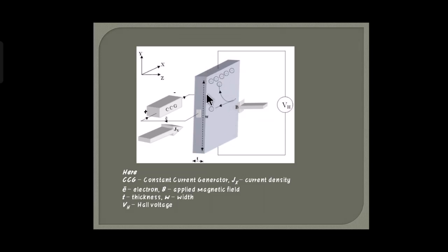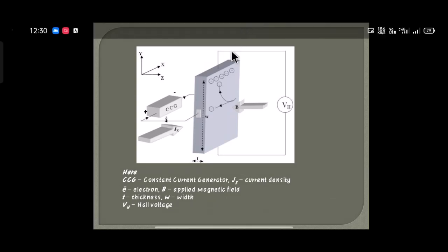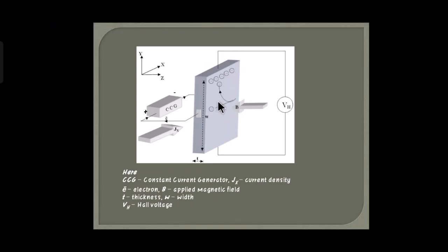This is known as the Hall effect. While we take the sample, during the Hall effect phenomenon, the concentration of electrons at one end is greater than at the other end. So if we take the potential across this end, we see that there is a sufficient potential difference across the opposite end, that is in the y direction.